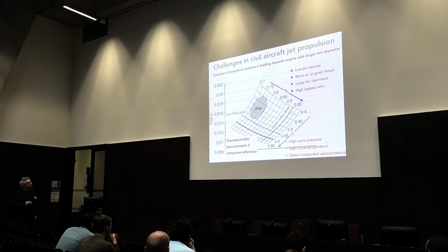If you want to go on the second avenue, so the thermal efficiency increase, you need to have high cycle pressure, meaning that you have to work very hard on the compressor. And today we already reach 93% efficiency for the compressor and a pressure ratio over 50, so it's quite hard to make any incremental progress on that.